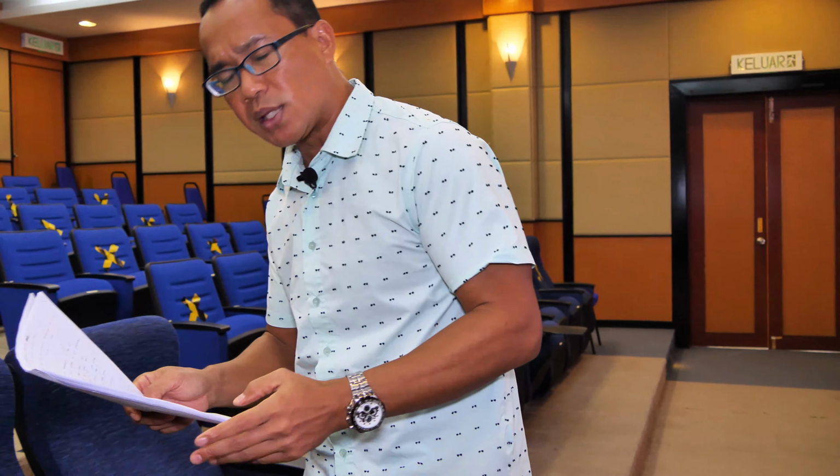So basically those are the six criteria that you need when you want to consider deploying your LED. Maybe I summarize. Number one, the pitch is very important depending on the distance. Pitch 2.5 or pitch 3 is suitable enough for an auditorium.